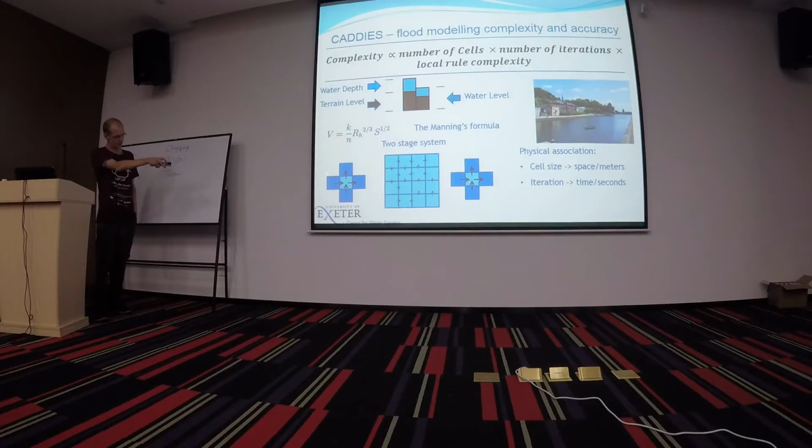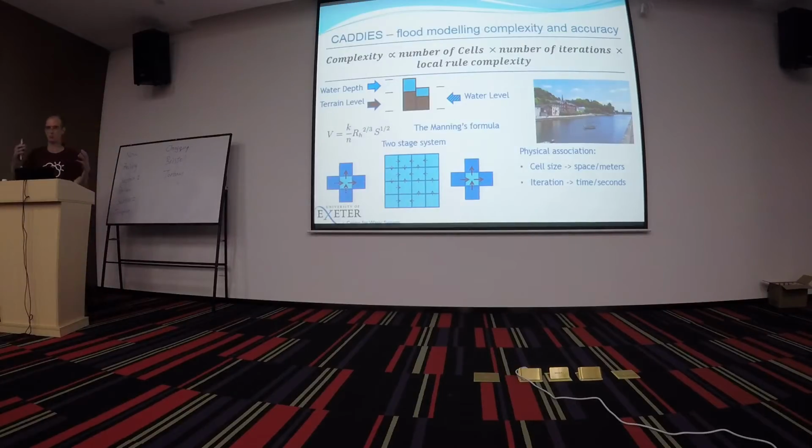So once we have calculated the outflows for all cells, we have outflows in all what we call edge buffers, which is the area between a pair of cells that it shares. Then in a second stage, we go through all the cells again in a similar way, and we simply remove an outflow and add an inflow. And because an inflow is also an outflow from another cell, that water should balance, unless we've got any going out of the terrain and we've got it open.